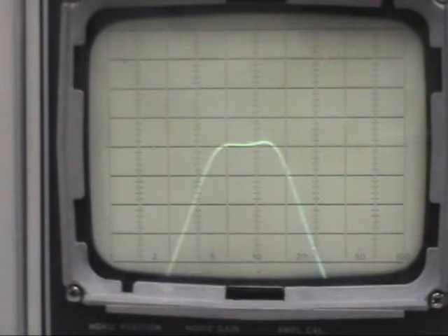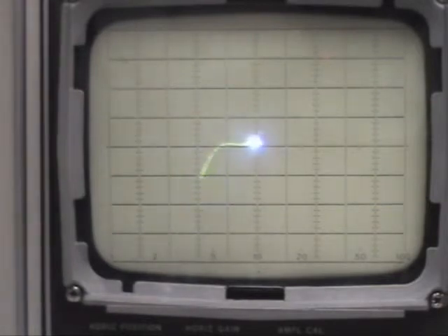So we'll go to manual sweep, and I can run it back and forth. We'll come up to where we're 1 division down, which is 2.5 dB. That's measuring 13.997. And we'll run to the other side, and that's 14.291. So we're just a little bit low with our adjustments. We'd need to adjust that up.